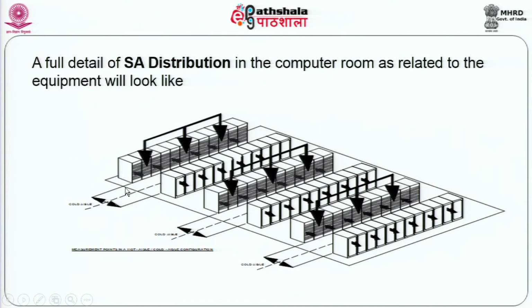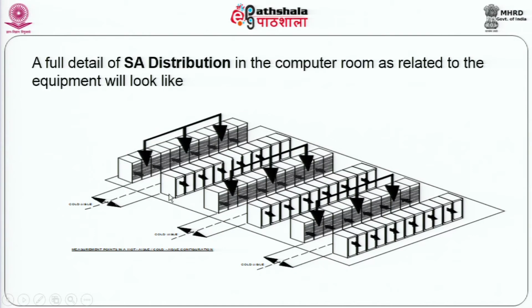So, in other words, one can decide upon having the front aisle of every machine as the cold aisle. So, that is the aisle where supply air is allowed. It can come from the top, it can come from the bottom, but this will become the cold aisle. The next cold aisle will be here. In between there will be an aisle which is meant for the service of racks, that will be called and categorized as the hot aisle. So, in other words, you have added a sort of a system to something which was not categorizable. To a data man, he will come and tell you, look, I will keep 60 servers one on top of the other, but you told him, look, I want to have a detail whereby I should be able to provide for the services.